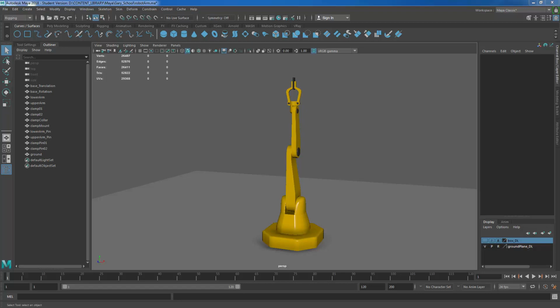One of those things would be if this object is intended to go into a video game, we want to combine as many objects as we can to minimize the number of draw calls on the engine. We also want to make sure we get all of our pivot locations set very carefully. And then we want to limit as much control so that the animator doesn't accidentally break the model in the animation process, and that the selection process of the handles is very easy.